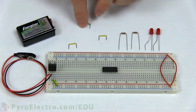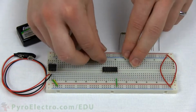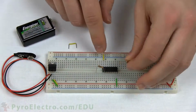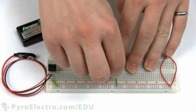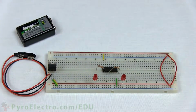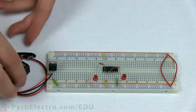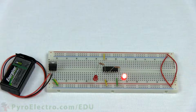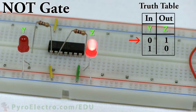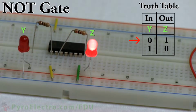For this circuit, we'll place the IC in the middle of the board and add power and ground connections. Then the two 100 ohm resistors are connected to pins 1 and 2, followed by two LEDs which connect from those resistors to ground. Finally, a yellow wire is added to give input to pin 1. Now you can see the input on the left-hand side and the output on the right-hand side. When logic 0 is connected to the input of the 74HC04 at pin 1, the output at pin 2 is a logic 1.